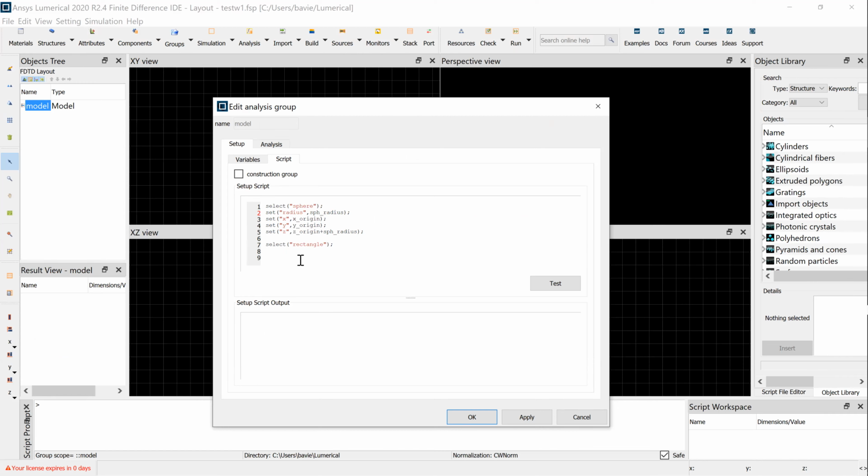So for the second object, we want to set up coordinates through the object center and coordinate span. We need to do it one by one for each of 3 coordinates, x, y, and z. So we type similar lines for the x and y spans using variables dx and dy.